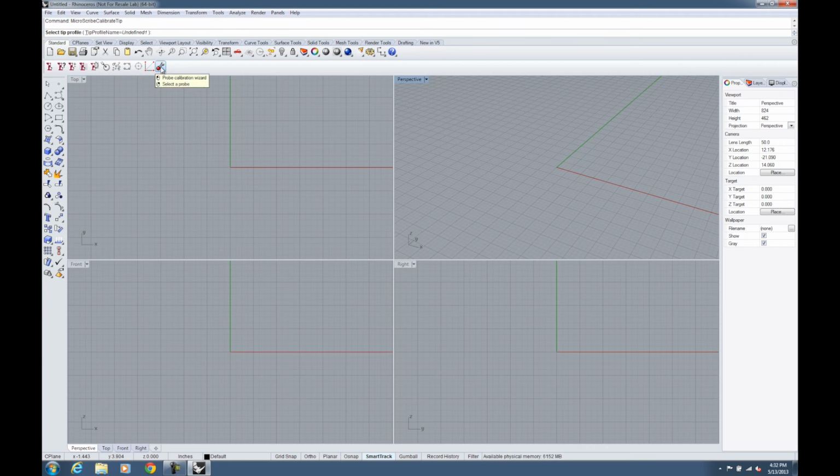So to do a probe calibration, we will left click on the probe calibration icon, and then we'll press our tip profile name equals undefined 1. So we'll go ahead and define undefined 1. So we'll enter our tip name, and we'll just call this 3mm.